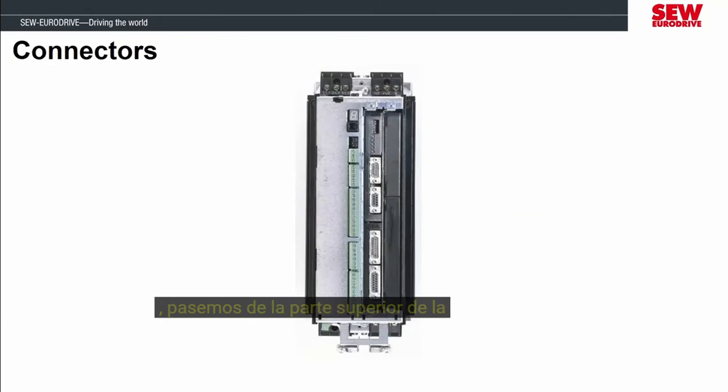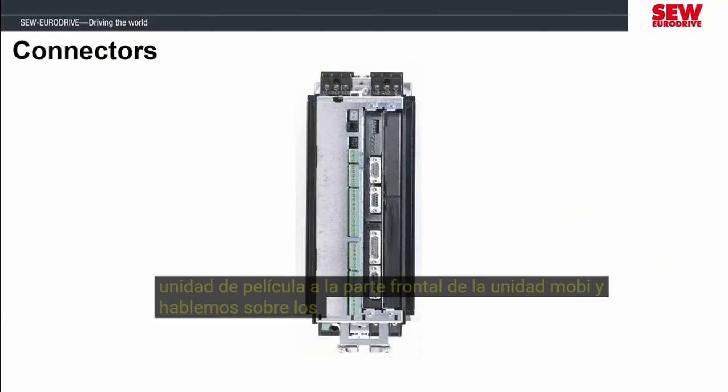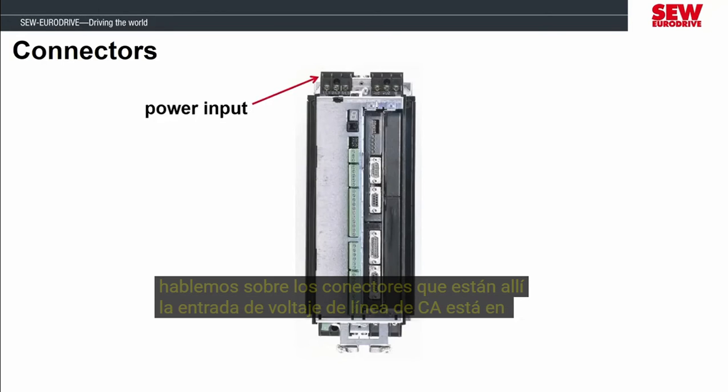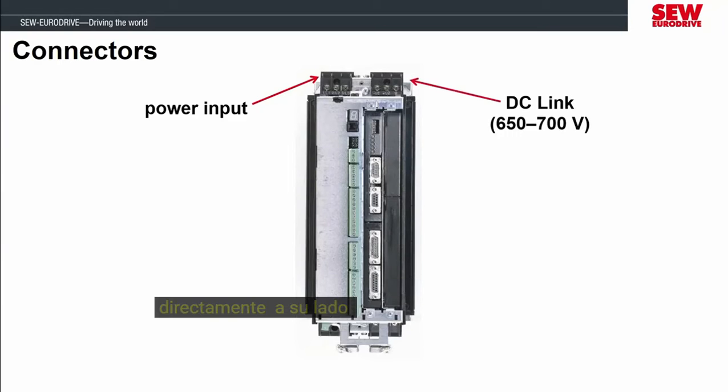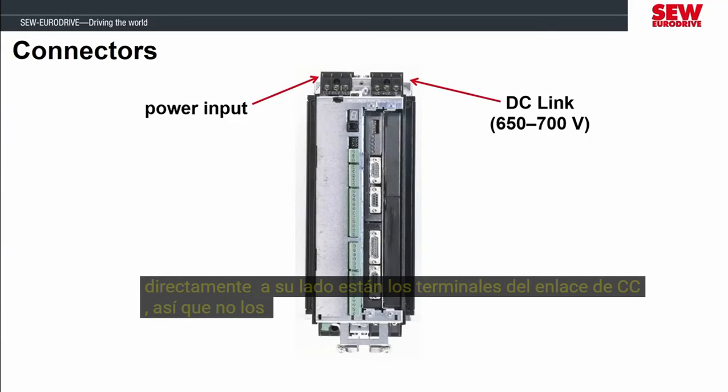Let's move from the top of the MOVIDRIVE to the front of the MOVIDRIVE and talk about the connectors that are there. The AC line voltage input is on the top of the MOVIDRIVE. Directly beside it are the DC link terminals, so don't get them mixed up.